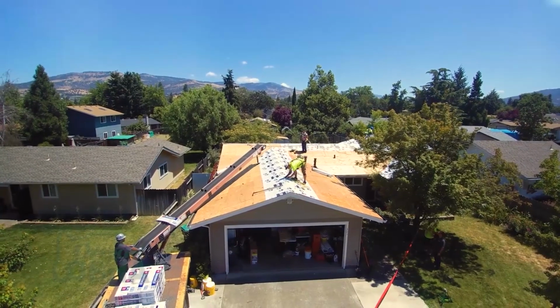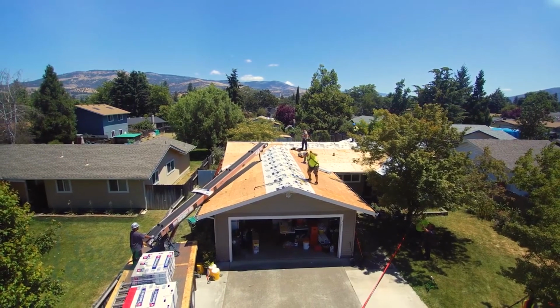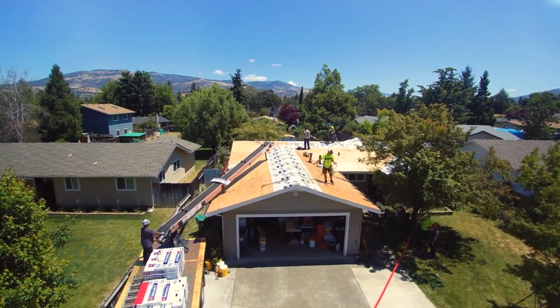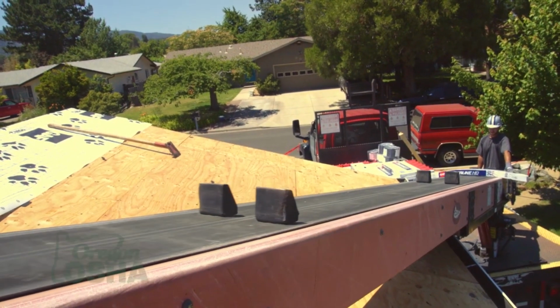When it comes to loading or unloading materials on a residential project, for example, we typically have our supplier deliver the shingles up on the roof. They have the boom trucks, they load it up there, but we typically bring out all the underlayment, the metal flashings, and so on and so forth. So when it comes to getting those things up on the roof, we typically try to hand them up if we can, because the underlayment's not heavy. We try to minimize what we can with the guys carrying stuff up the ladders and across the roofs. It's already a hard job, so we have our suppliers load the materials to the job.